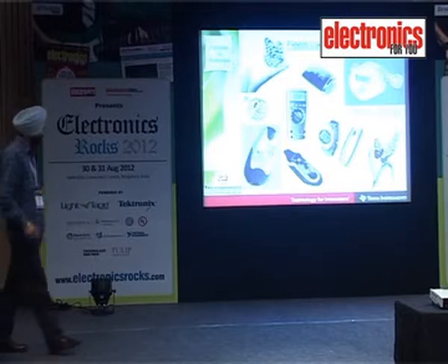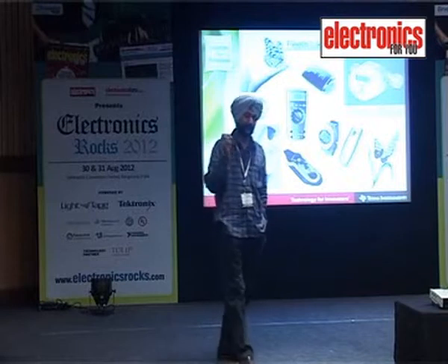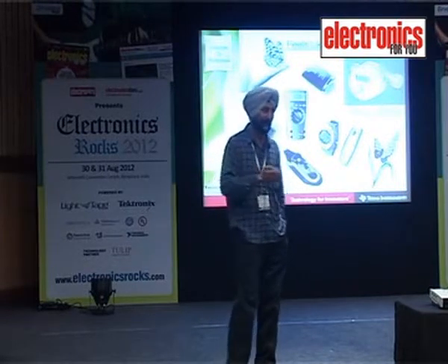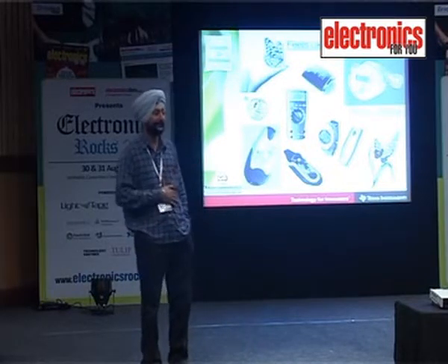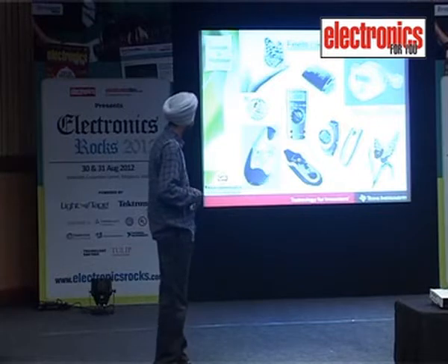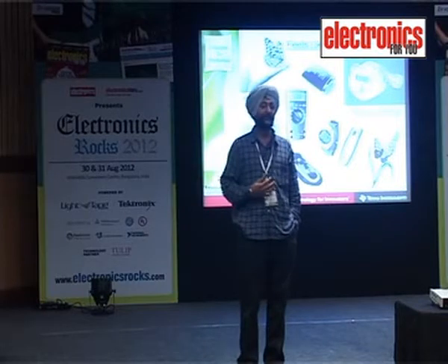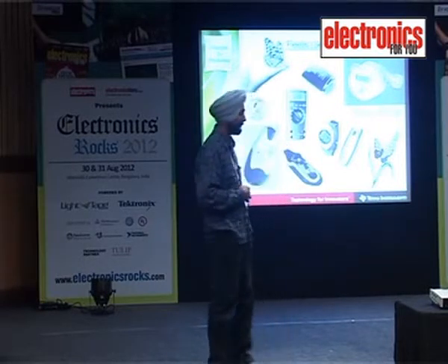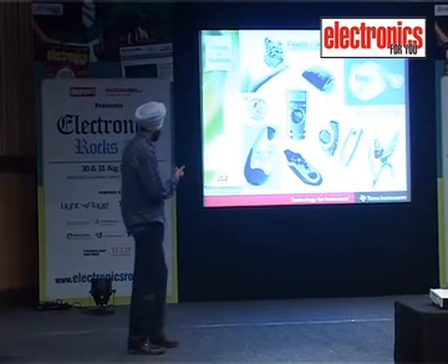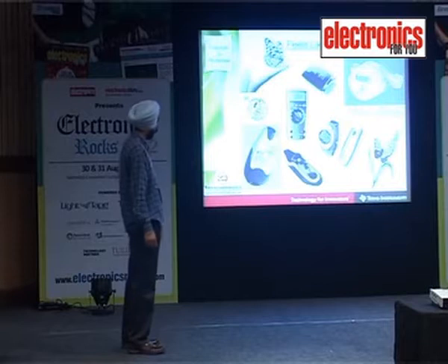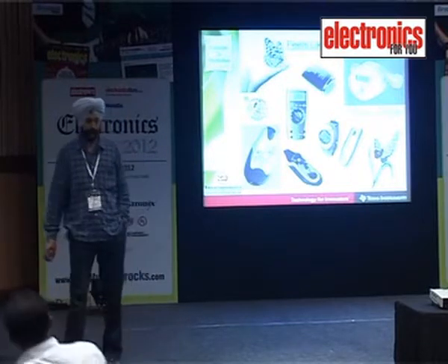Now when it comes to the look and feel, it feels like a butterfly because the chipsets are so lightweight, very small in size, takes less power. You can find this in your Fluke multimeter, world's number one multimeter company. These meters are powered by MSP430. You can find water meters where you can use MSP430 continuously for 10 years, right? Because power consumption is very, very critical in these kinds of applications. You can find MSP430 in HVAC systems, in the remote controls. Even nowadays, TI is having a special protocol for the remote controls.